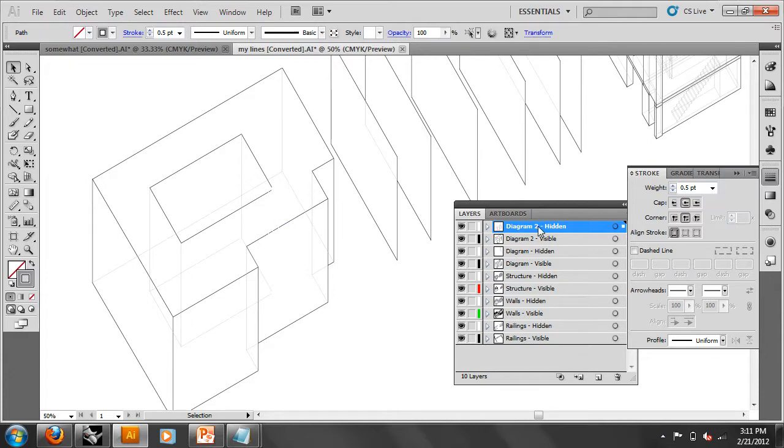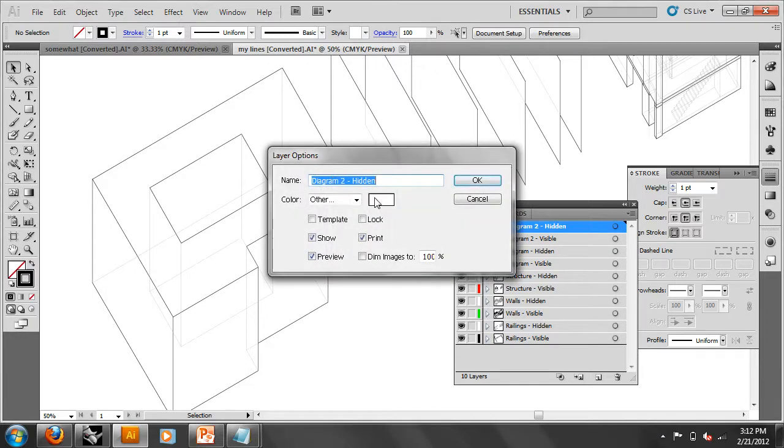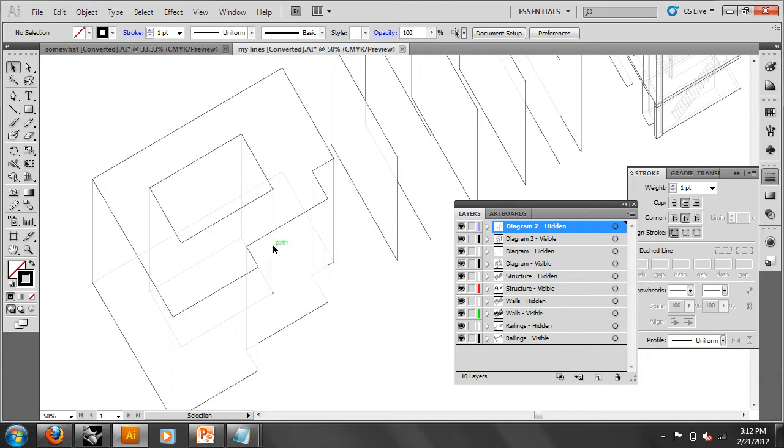Oh, another thing too, guys, with the layers that are white like that, in Illustrator, when you pick something, it uses the color of the layer to do the selection window. So I think I showed you this. You want to double click that layer and change the color swatch to something that reads, like orange or lavender or whatever, instead of white. See now it's purple instead of white. So pick these lines, and I'm holding shift when I do this.